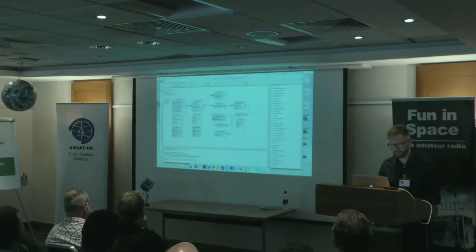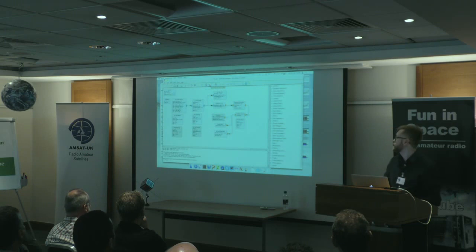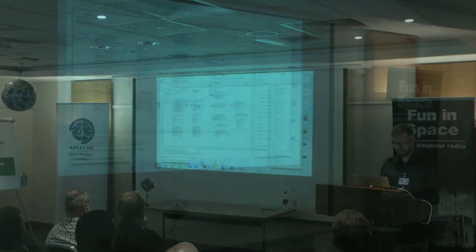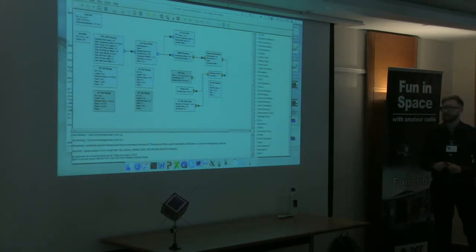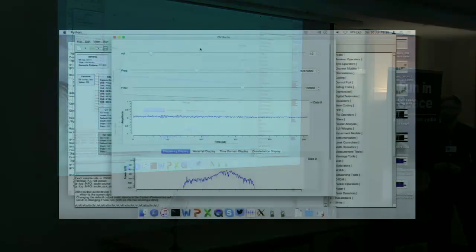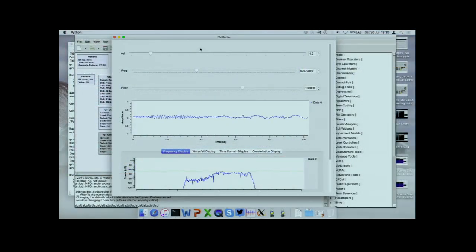This is what GNU Radio looks like. And when you hit this button here, it says Generate Flow Graph. When you hit that one, that will be generating our Python file. And then when you hit play, everyone cross everything. You can start to then see what you've then got output. Now, let me turn up my volume.